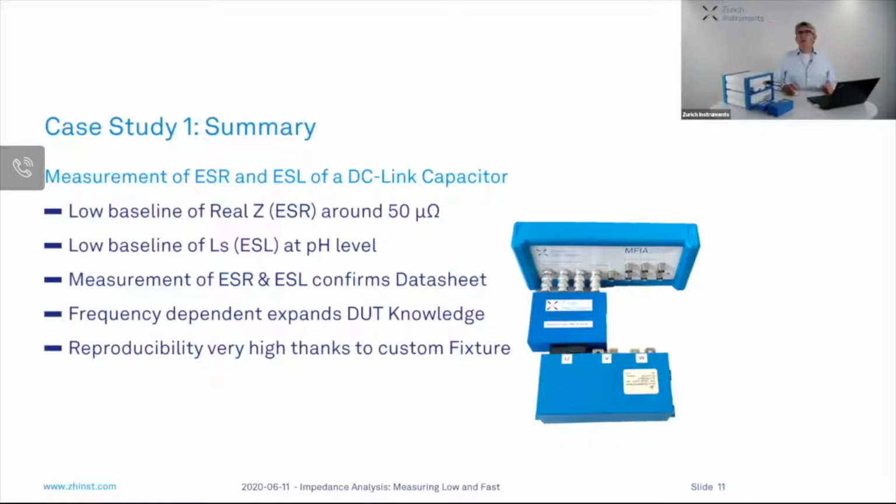Then we measured and confirmed both the ESR and ESL to be within specified values of the datasheet. But what's more, we measured this over a wide frequency range and measured how the ESR and ESL change with frequency. And finally, we also demonstrated very high reproducibility when disconnecting and reconnecting. So that brings this demo to an end. Now we can move to the question and answer session.